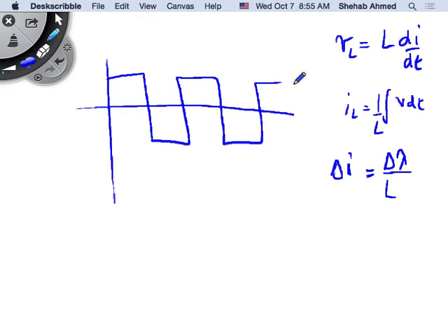I cannot keep increasing. If I keep building up the magnetic field or adding more current to increase the flux, what happens to the core that I'm winding the wires on? It will saturate, right? I mean, even air saturates. It has a certain amount of flux density, or a core of a magnetic material will have a certain amount of flux lines that can go through it. Beyond that, you're pushing more current into the windings, but your core is saturated.